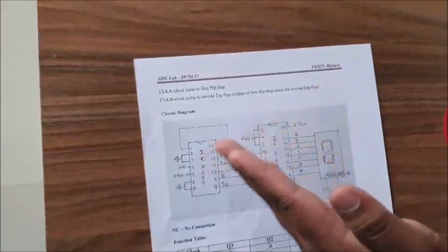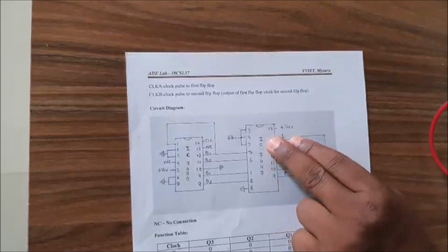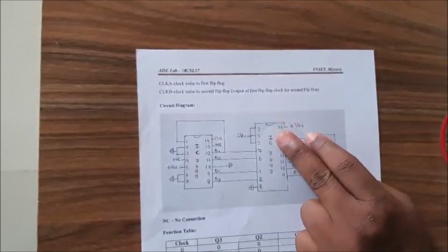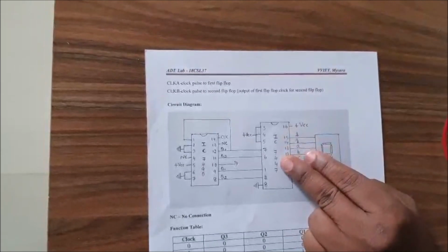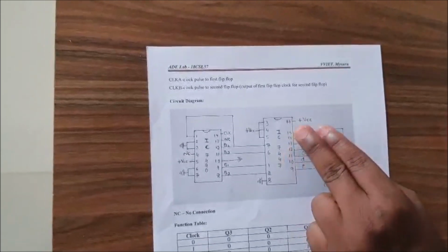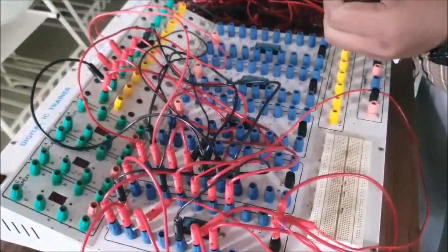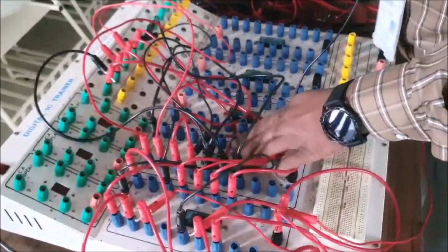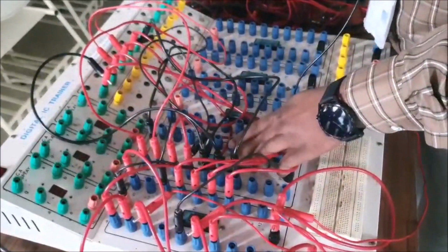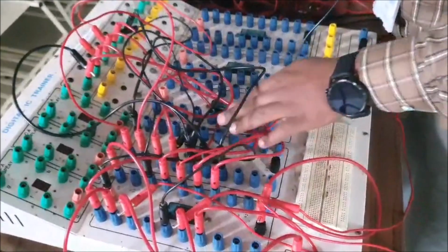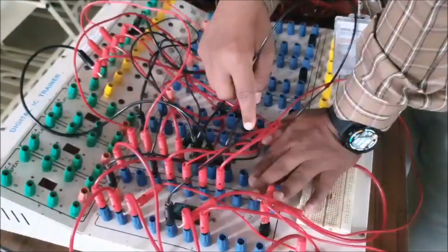So now moving on to the right hand side of 7447, we have a 16th pin, where we need to connect the 16th pin to the plus VCC of this 7447 IC. So now I will take one patch cord. One end of the patch cord is connected to the 16th pin. So here, coming to the 7447 IC, there are total 16 pins in this IC, 8 pins on each side, which means that on the left hand side we have 8 pins.